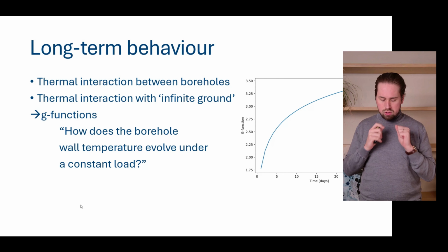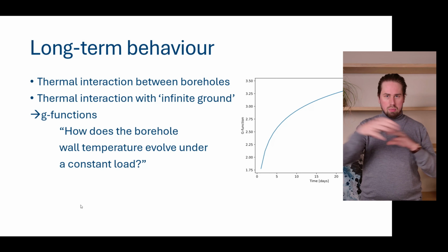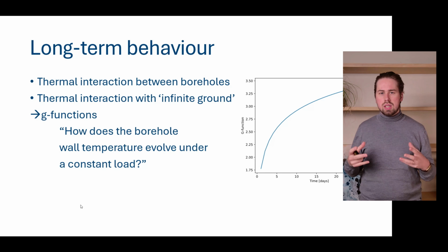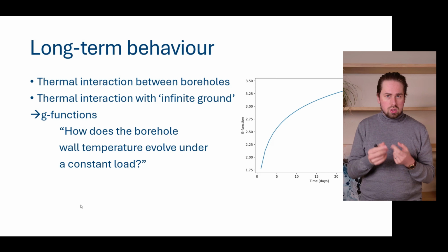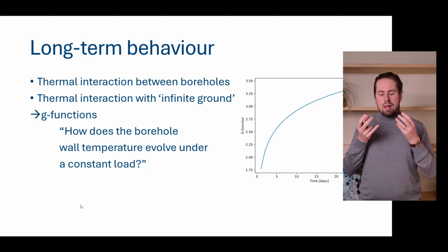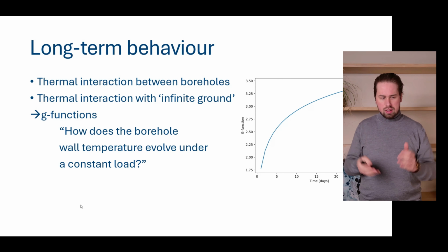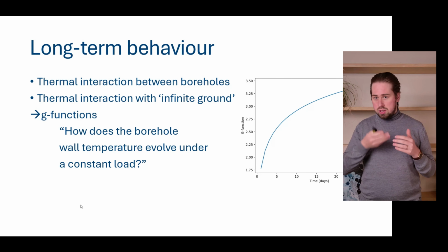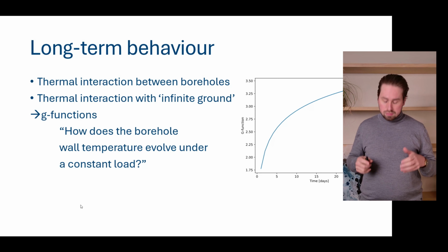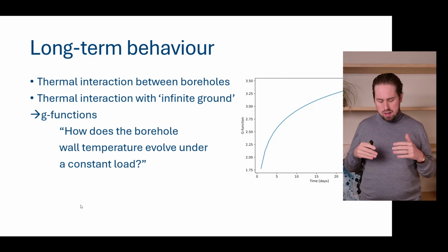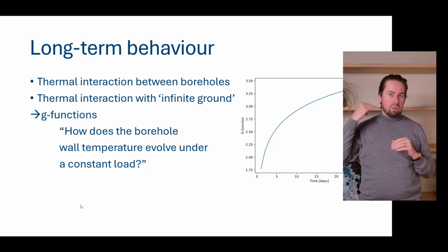So what we try to conceptualize is that every bore field, every configuration, every depth, every geology has its own unique fingerprint, its unique G-function. If we have this bore field and we inject a constant power into it, let's say 1 kilowatt, how will the system react? As you can see on the slide, if we inject heat, the ground heats up, and in the beginning it heats up faster.